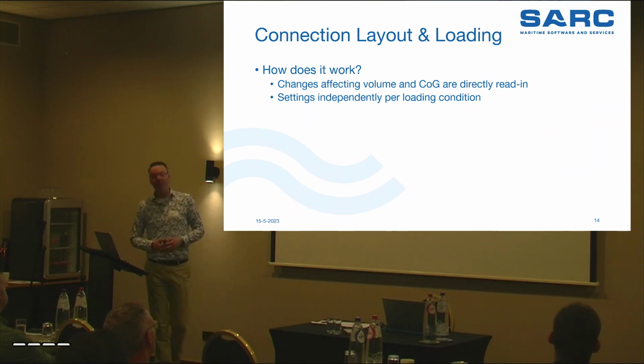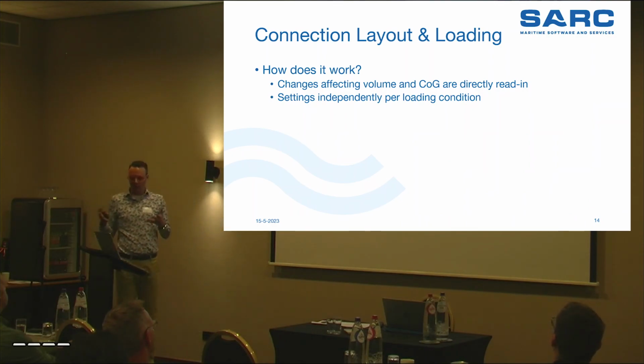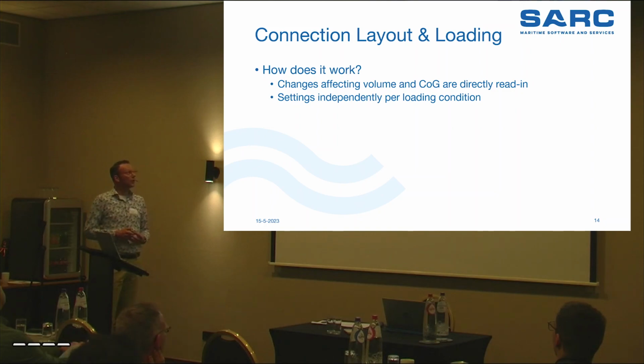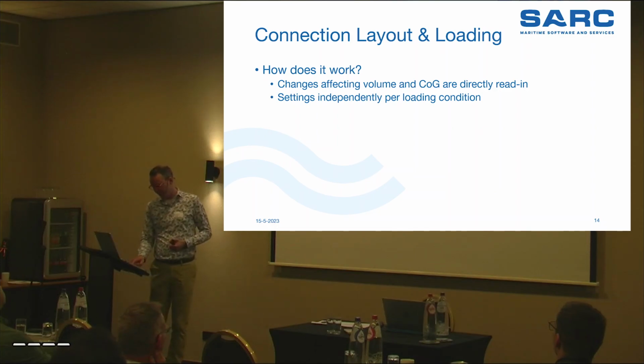Right. Connection between layout and loading. Up until last year, we had the function where things needed to be reread by using a button. That is now not necessary anymore. The reading from tanks is now directly done when entering layout. The advantage of this is that changes affecting volume and center of gravity are directly read in. And now also settings can be made independently per loading condition.